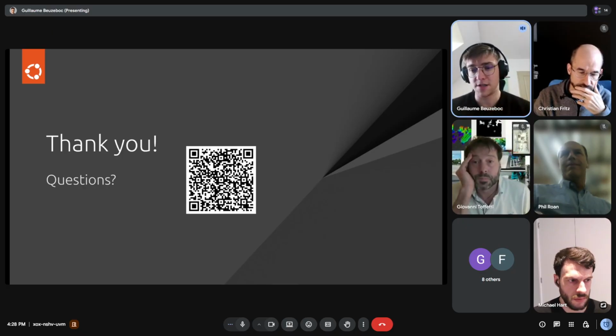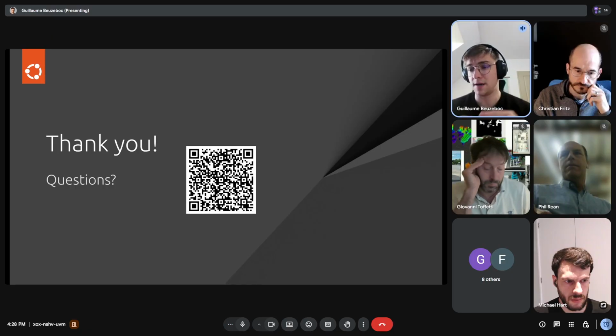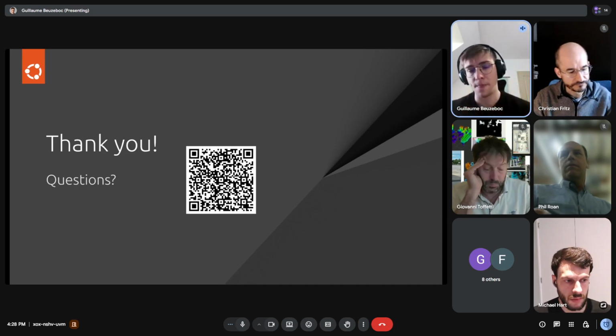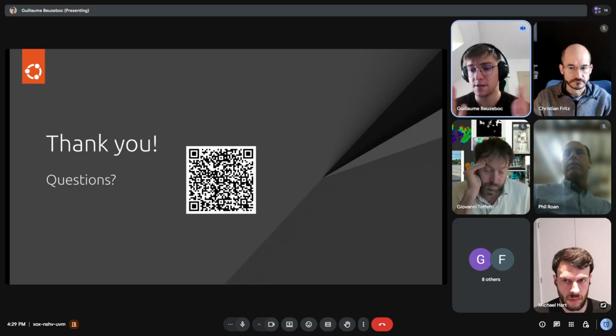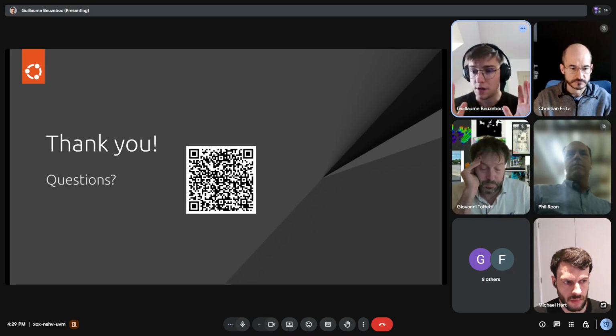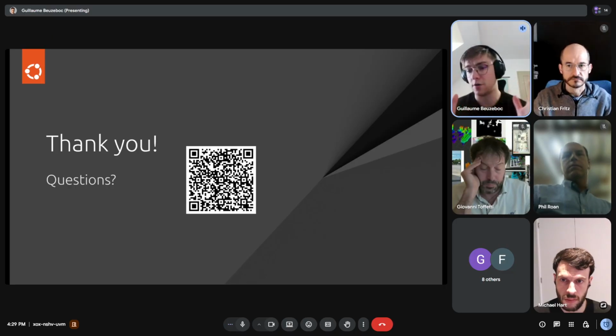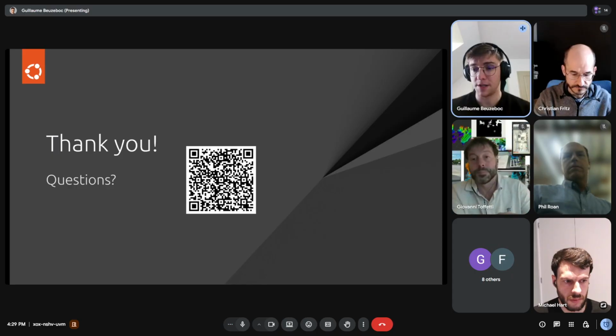And the second one is this ROS bag exporter. So we are offering to constantly record ROS bags and sync them on the server. Similarly, there you can specify the topics that you want, and you can even specify the maximum size of the bag or duration that you want. This way you can just, let's say after 2 minutes or 200 megabytes of data, stop the recording, upload the file, and start a new recording in parallel. But yeah, that's really up to the usage of everyone and how much storage and bandwidth you can afford.